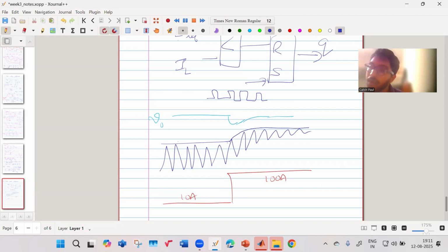Now, when you have feed forward control, suppose your reference was like this. As the load changes, your reference will immediately change, because it is detecting the load directly, proportionally. When your reference changes, your current also will change directly and fast, and your output voltage will have a slightly smaller, faster dip. So it is less dependent on load current. That is, your output voltage deviation is much, much smaller when you have load current feed forward. So this is the advantage.